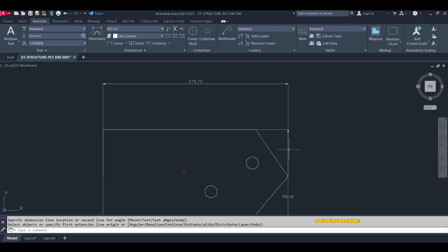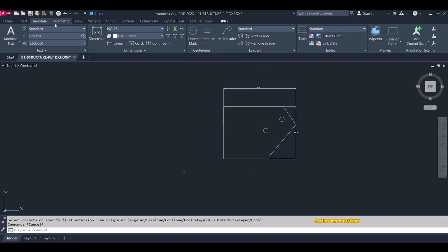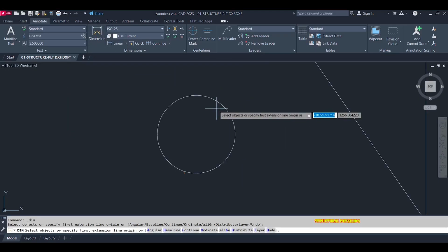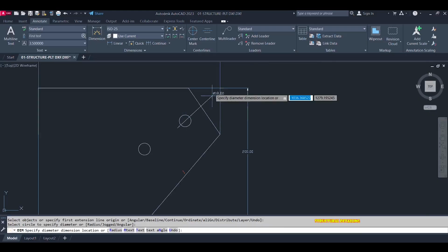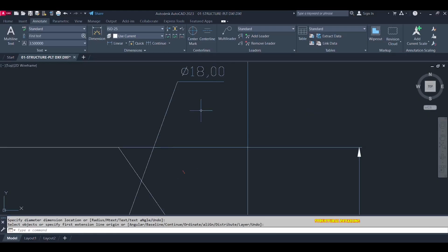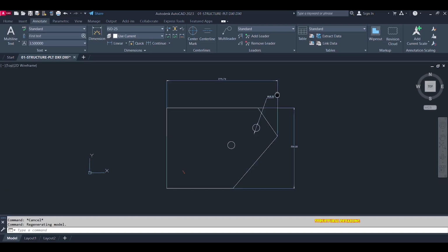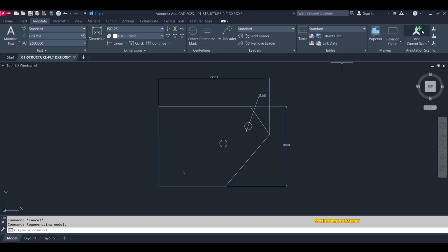So if you check our tutorial, if you check our thing back there, because I closed SolidWorks, guys, I just wanted to show you that it opens, so you can just reference it to the other plate. And even our holes are still intact. You still have the diameter that we had as 18 there, you see. So it does work. So this is also how you convert your SolidWorks drawings to AutoCAD.